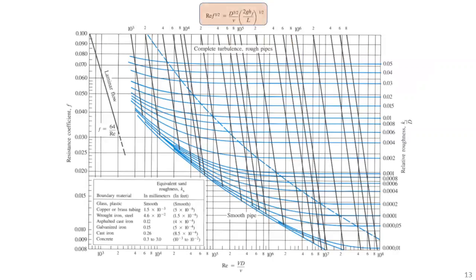So now we have 2 coordinates with which we can enter that Moody diagram. From the top, we know that Re f to the 1/2 is 48,200. From the right, and you can see I drew that contour, and obviously it doesn't have a value right on one of the black lines. And so you're visually looking in between the two. Using the computer graphics, I can make it look parallel, but when you're just using your eyeballs, you're just trying to bring that line down parallel between any of the other 2 black contours.